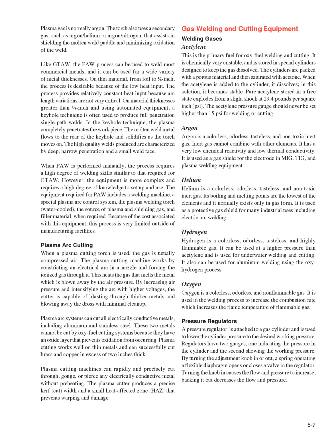Pure acetylene stored in a free state explodes from a slight shock at 29.4 pounds per square inch, psi. The acetylene pressure gauge should never be set higher than 15 pounds per square inch for welding or cutting.